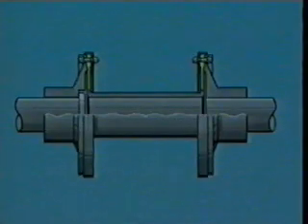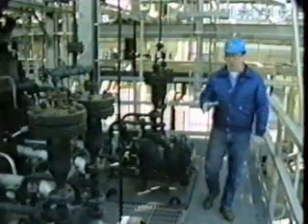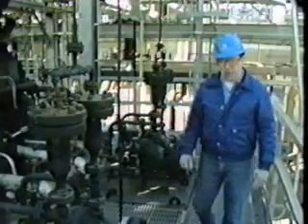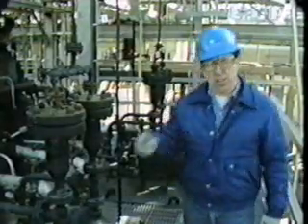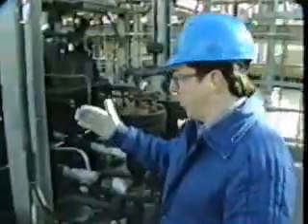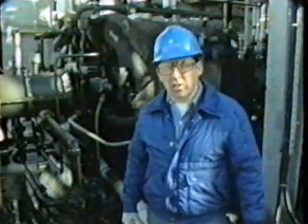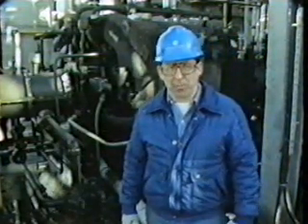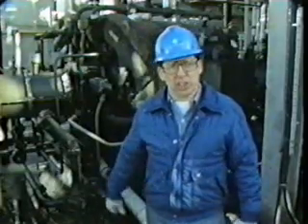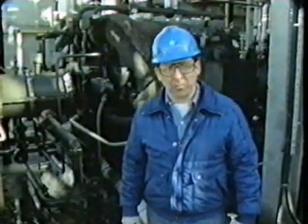These couplings can handle fairly large angles of misalignment between shafts. However, this coupling can tolerate only slight changes in back and forth movement of shafts. There are several factors that affect performance of the compressor. For example, varying the speed of the compressor will vary the volume of gas moving through it. Recycling gas back to the suction side will also alter the performance characteristics of the compressor. So in this way, operators can achieve different results for the compressor.